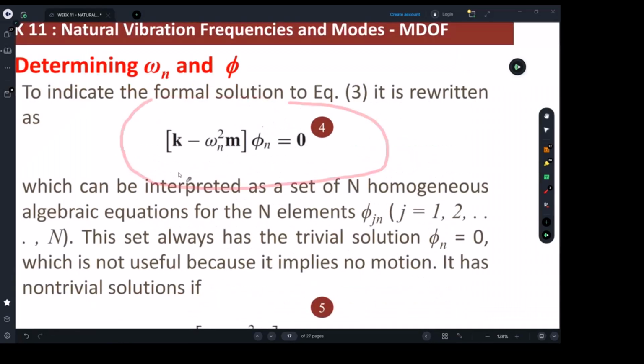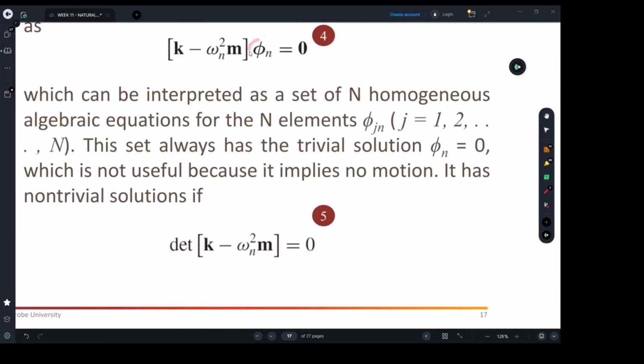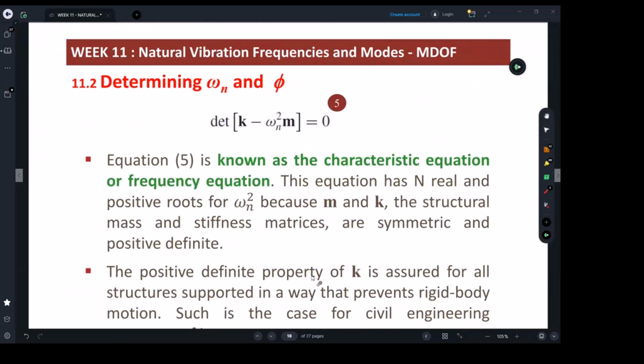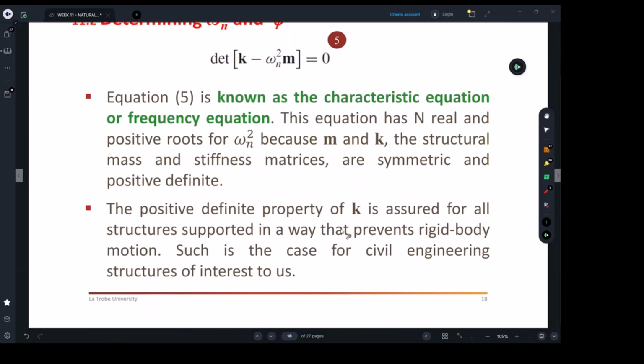So the harmonic motion was achieved by equating this equation to 0. Now we all agree that phi cannot be 0 because there is a vibration and there is a shape. Then the other option we have is to solve the equation further, and put this term equal to 0. Now this equation is ready for us to determine the frequency, whether mode shape 1 or mode shape 2. And from frequency, we can find time 1 and time 2.